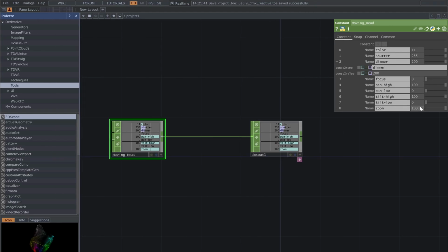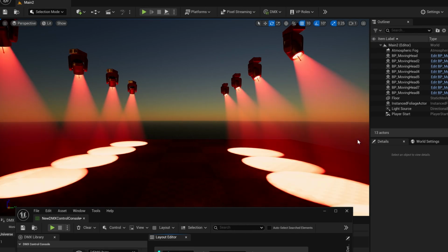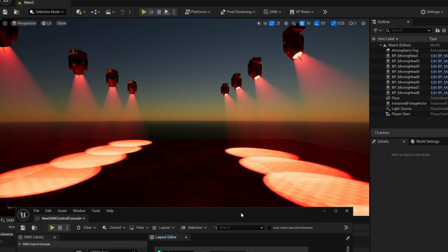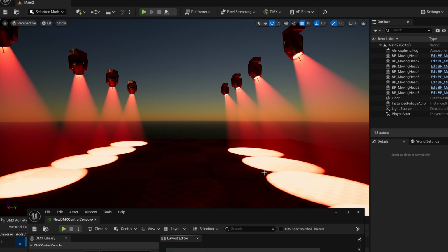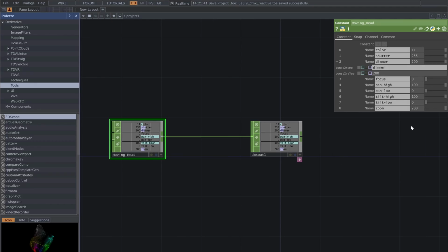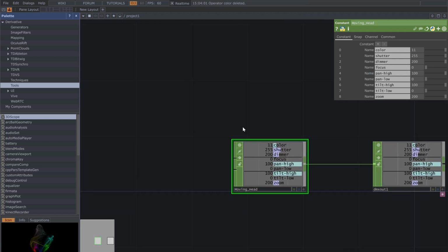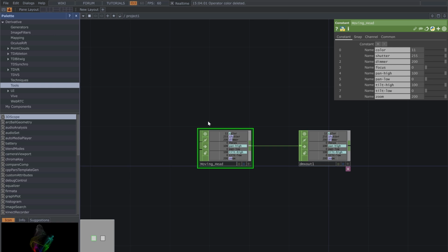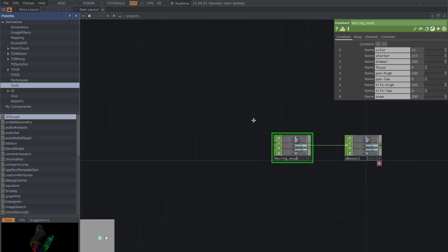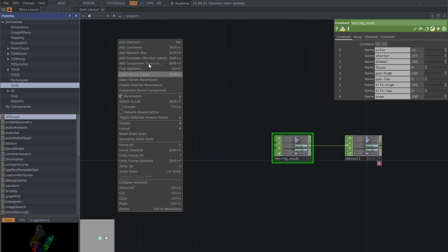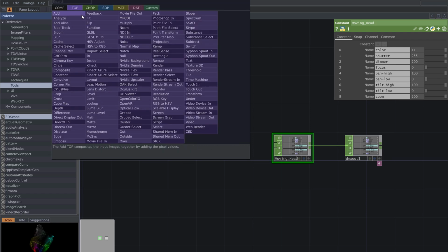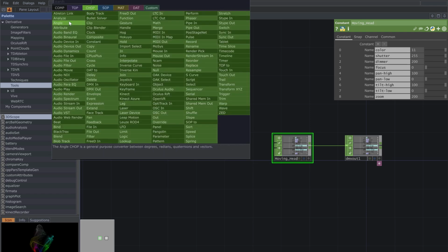So everything's connected. Now we head into the hard part, where we refine the data to allow these lights to look good as we analyze the audio input and convert that to DMX data. There are some quirks in here because the numbers that you saw on the controller are 0 to 255, and so the audio settings, you have to tweak those in order to get them up into the range that you want. So we're going to use math operators. But first, let's get in here and get some audio so that we can have something to work with.